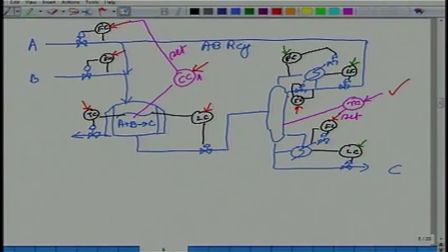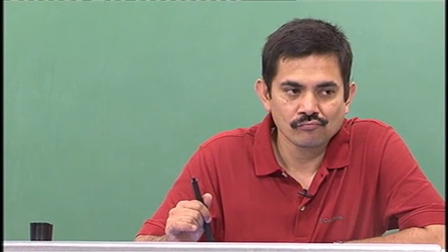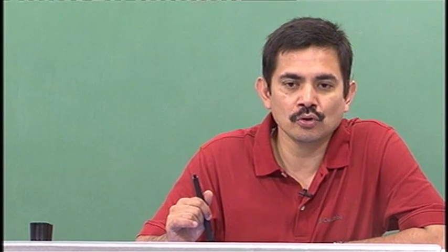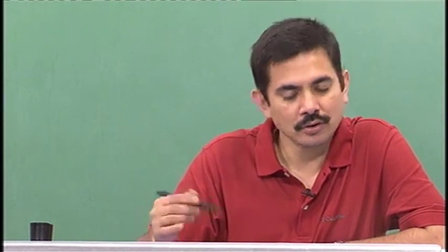What should my level set point in the reactor be? Maximum allowable. Why? Maximum residence time, more reaction. So conversion is more, so what? I mean you have to keep answering so what until, so, huh? More easy.